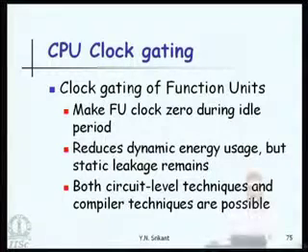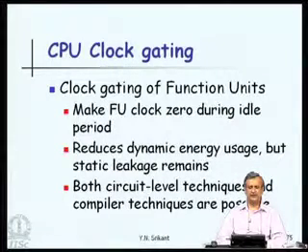Then I mentioned CPU clock gating. Gating implies stopping. So, the clock to the function units is stopped, which implies that the function unit cannot run at all. These are all synchronous systems, so they require a clock in order to run. We make the function unit clock 0 during the idle period.